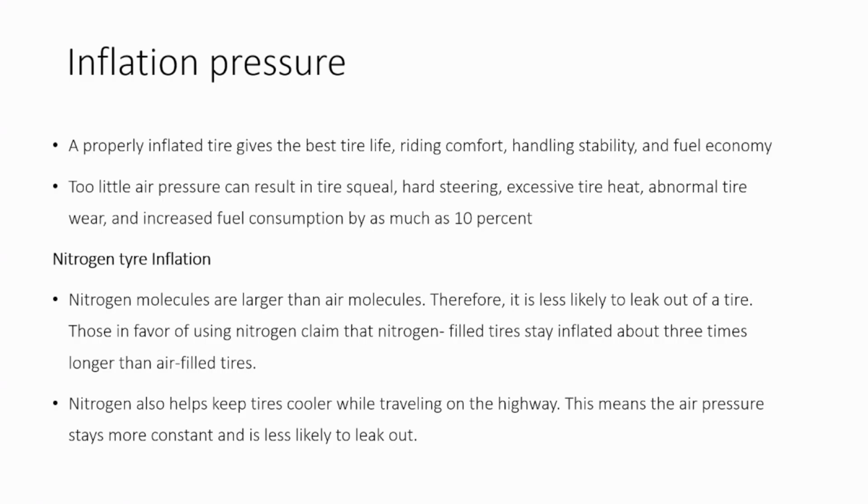And also the riding comfort, the suspension system will be working properly with the correct inflation pressure, and the stability will be increased, and ultimately fuel economy will be increased, which means that the pressure should be in the correct range, where it should not be lower or higher, right?